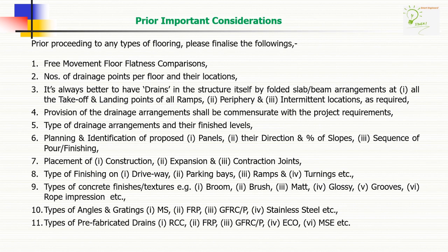Prior important considerations. Prior to proceeding to any type of flooring, please finalize the following: free movement floor flatness comparisons, number of drainage points per floor and their locations. It's always better to have drainage in the structure itself by folded slab or beam arrangements at all strategic locations.